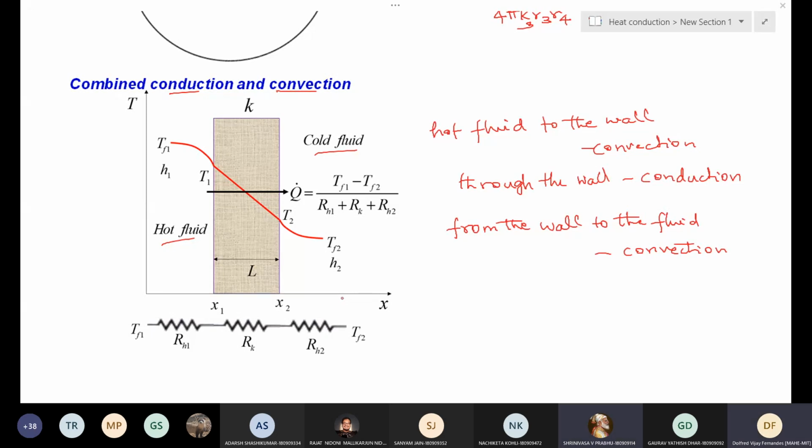Yes, of course, there is radiation heat transfer also involved most of the time, and we have to make some simplifying assumptions by comparing the magnitude of convection and radiation heat transfer to the wall. In many applications, we will find that radiation heat transfer is comparatively smaller than convection heat transfer, and we can neglect it. You can also understand that by remembering the Stefan-Boltzmann law, right?